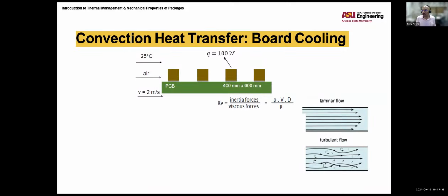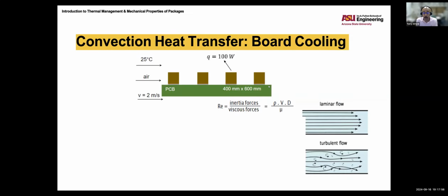So just as a rule of thumb, as far as we're concerned, we won't do it. You can read it in the textbook. Just this Reynolds number, we'll just say this thing 4,000. Above 4,000, we're going to get mixed laminar and turbulent flow. Less than 4,000, say 1,000, 2,000 or less, will be in the laminar flow regime.